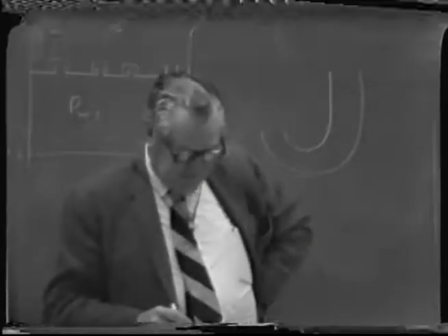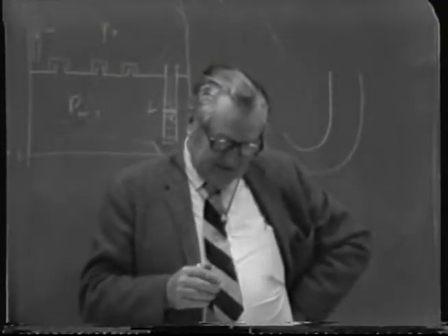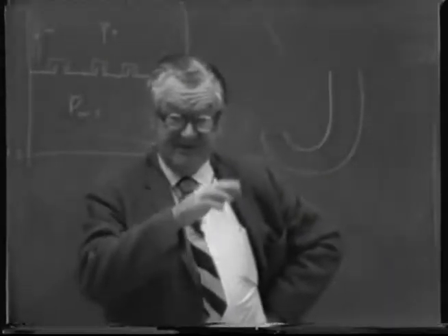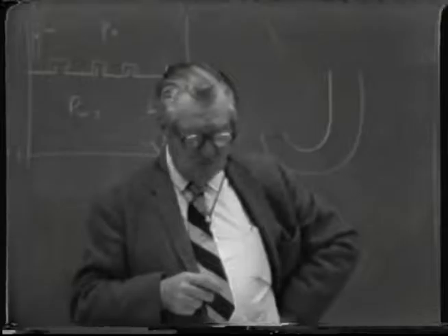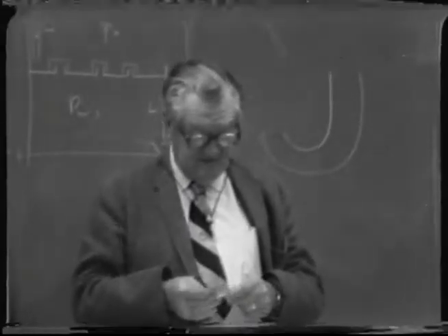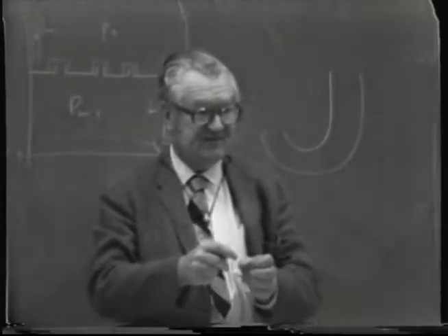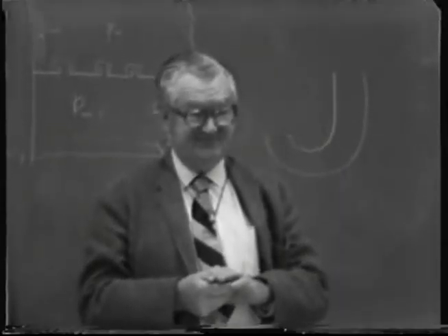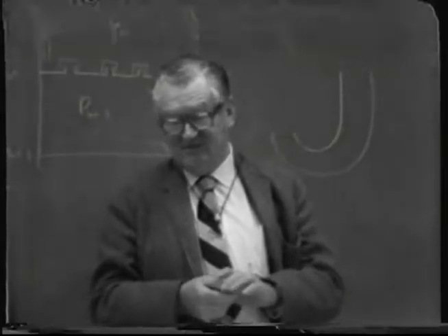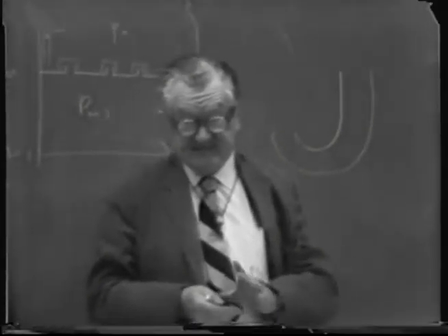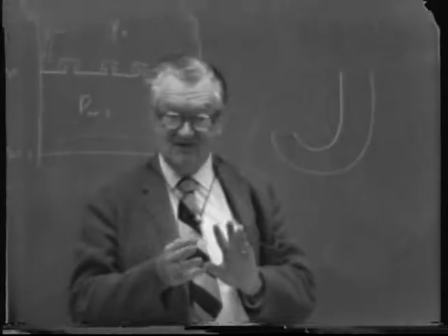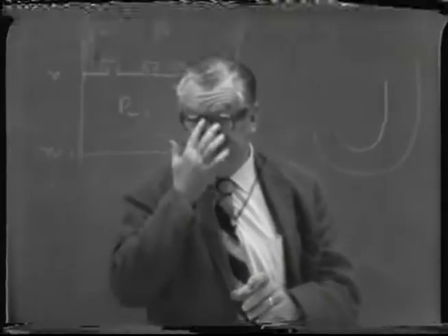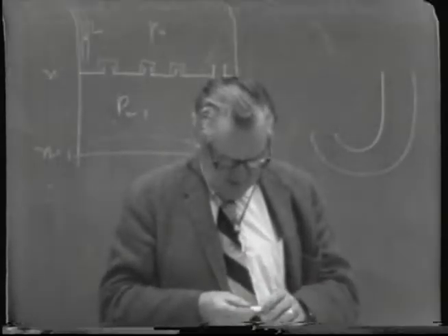Some people, I don't know whether this particular plant did it, but some people had this kind of a problem, so they thought, well, the holes aren't big enough. These are perforated trays, in the stripping section. So they drilled out the holes bigger than they should be, which is about 5/16 inch. It can be slightly larger, sometimes lower, depending on how coarse the soluble solids are that have to be handled.